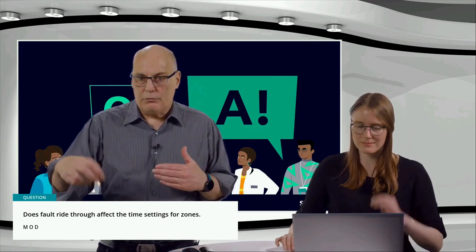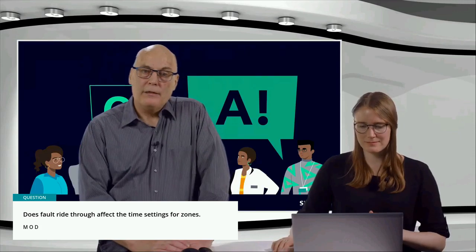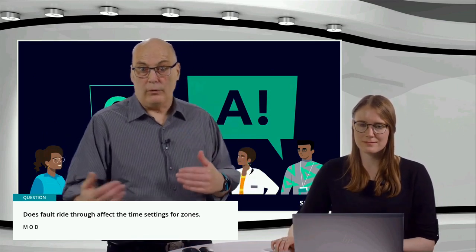Now, that could be that you have a T along a line and the generator or windmill feeding on as a T onto a line is set to fault ride through, then obviously that is going to affect your auto reclosure decision, because you would not want to do an auto reclosure onto the generator still connected to a faulted line. And fault ride through should then in that case not be set on. It should be to separate during a fault. So the method of doing the renewables is a different subject. But other than that, I cannot relate fault ride through to a zone time setting.